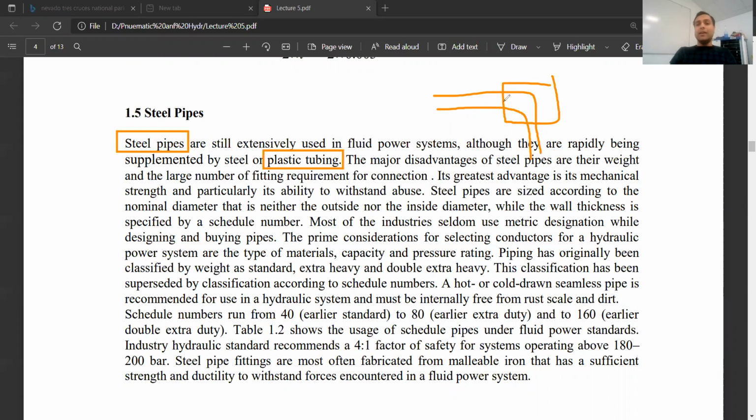When it's tight, it will put an extra stress on the corner, on the pipe here and here. So this results in residual or inbuilt stresses in the material, which will decrease the working efficiency or working pressure or working stress of this steel pipe anyway.